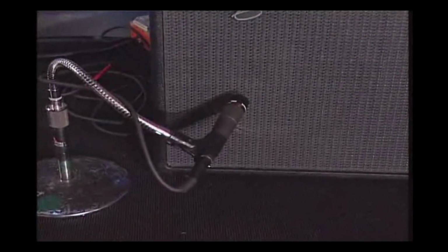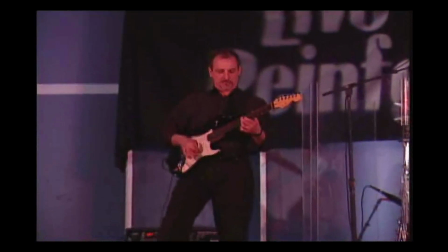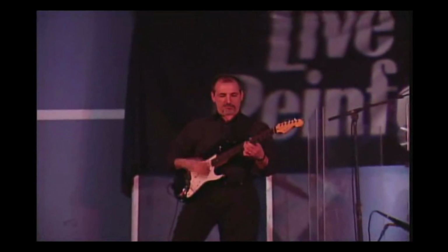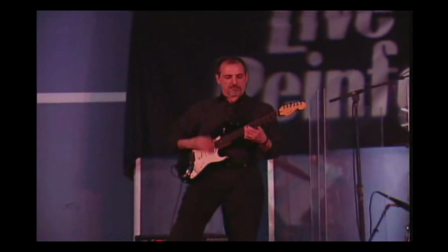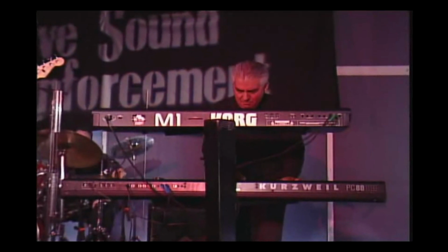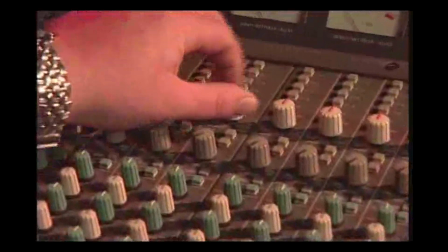Your goal here is to get as much of the guitar output into the PA as opposed to coming directly off the stage. You may have to adjust the speaker cabinet or increase the signal in the player's monitor in order to achieve this. For the keyboard player, typically the EQ is left flat at the mixer. The keyboard channels are panned hard left and right for each keyboard or for the keyboard submixer outputs.